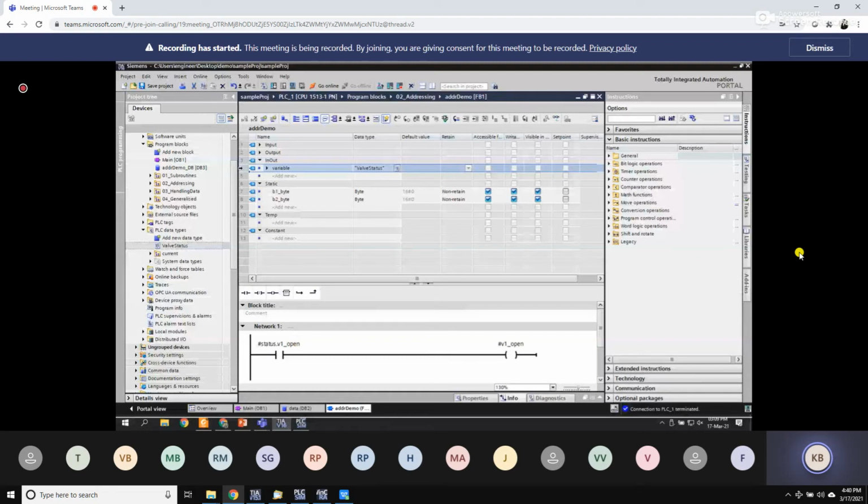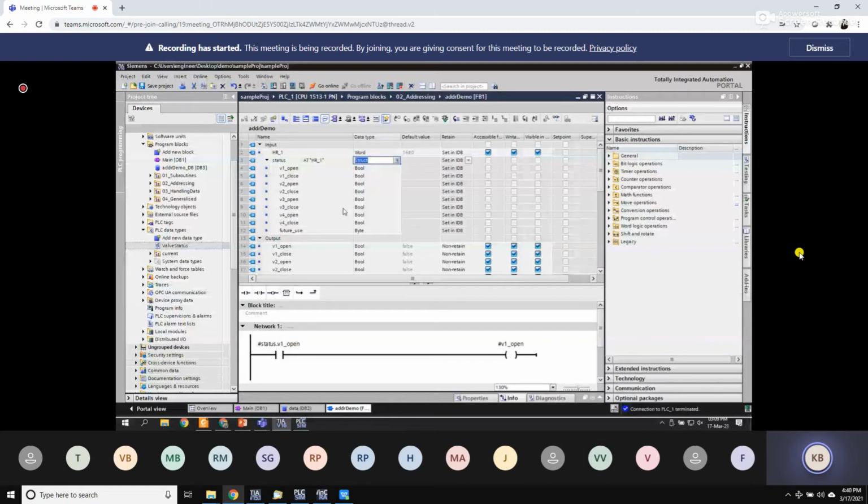So if you have another holding register where you would like to use the same concept, you can make use of this again over there. UDT is another topic that we are starting to discuss now, and it has many more features and facilities available along with that. The concept of UDT can be used not only inside your DBs, FBs and all, it can even be used natively with your IO memory as well.